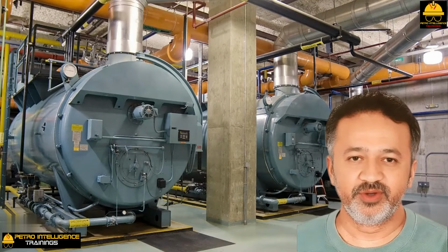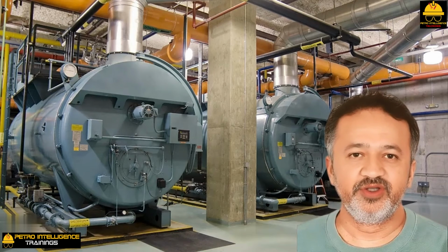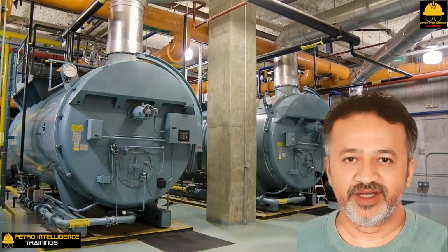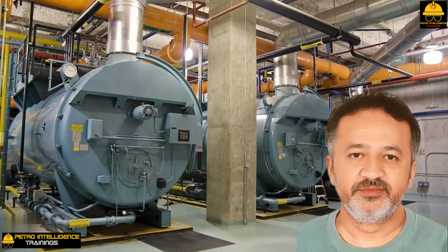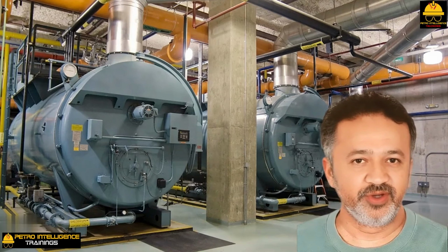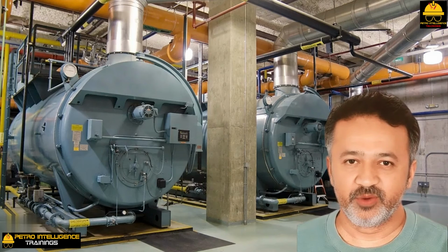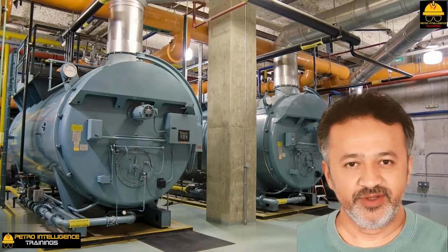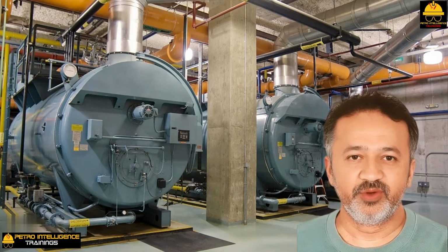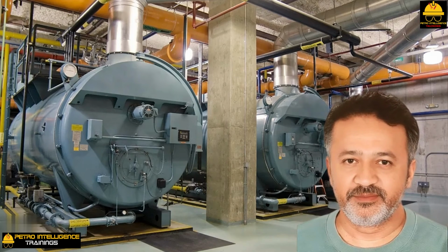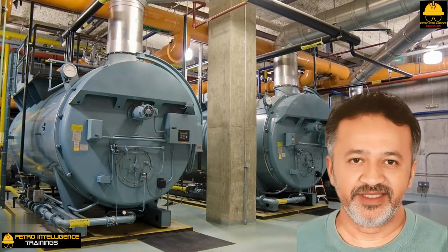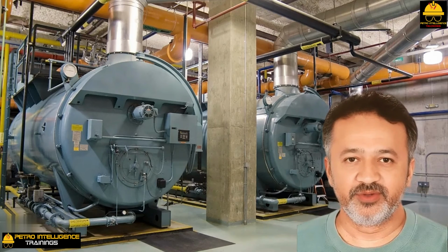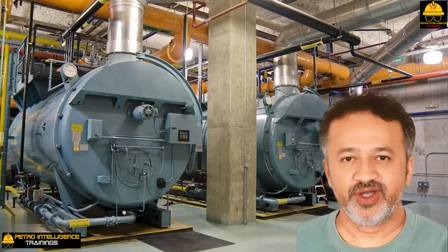Adjusting excess O2. At an oil refinery, I first learned how to optimize the excess oxygen content of the flue gas from a boiler. The fired boiler was equipped with a forced draft (FD) fan. Due to mechanical deficiencies of the FD blower, the combustion air supply was limited but constant. The boiler produced 650 psig steam, which was in short supply in the refinery. Hence, the boiler was operated to maximize steam production. The utility plant operators would routinely adjust the fuel gas supply to maximize steam production.